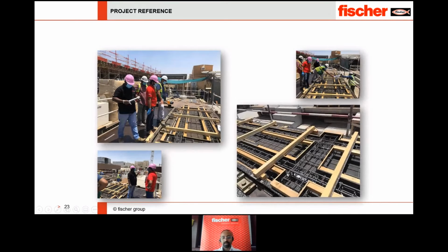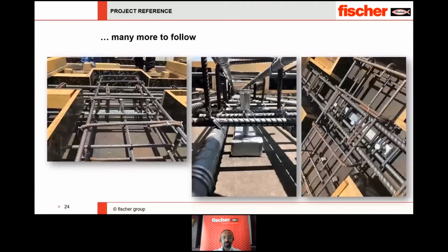You can see here the channels are connected to the plywood, which is the temporary formwork, and also connected to the reinforcement bars. This is a much closer picture. You can see the channel linked to the reinforcement bars to prevent it from moving while you pour concrete, and after the concrete is cured, this stays in place throughout the lifetime of the building.